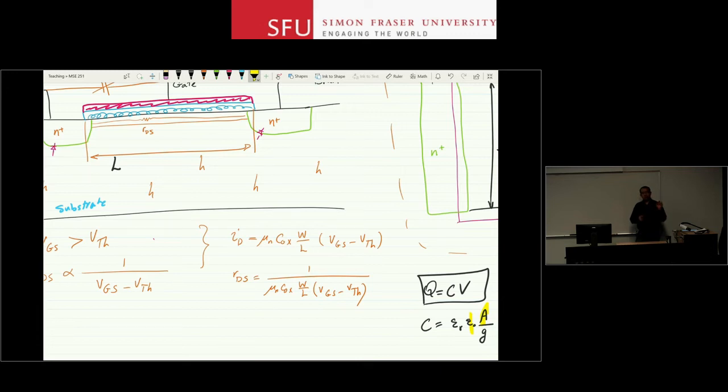You want to use materials that have a really high dielectric constant so that you can store more charge on this capacitor. You also want to make that layer as thin as you can before you increase your yield problems, so that again the same thing happens. So C oxide here is a measure of how efficient that structure is in bringing in these, let's say, electrons in this case to the surface and storing them at that location.